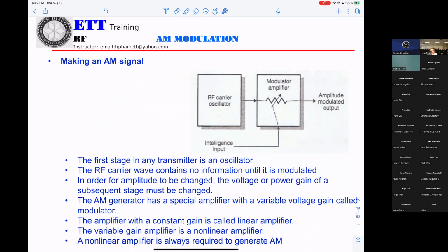When you connect power, the signal comes out at 1 megahertz. That means with a different oscillator, you can get a different frequency. That's why when you want to buy an oscillator, they will ask you what frequency you want.